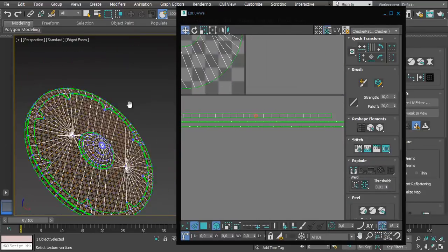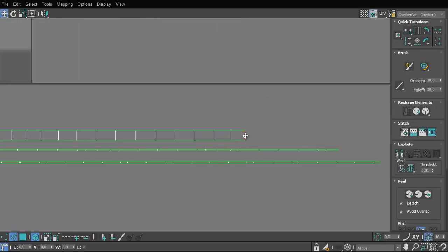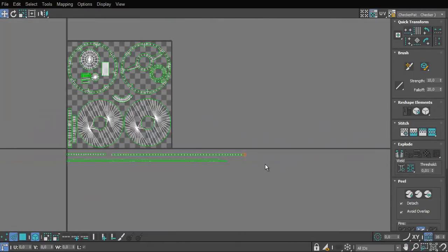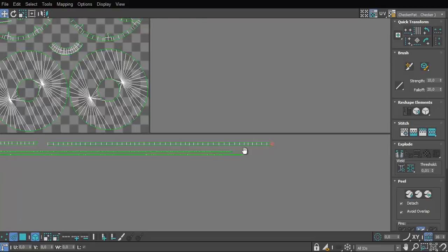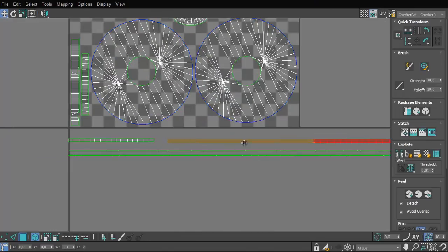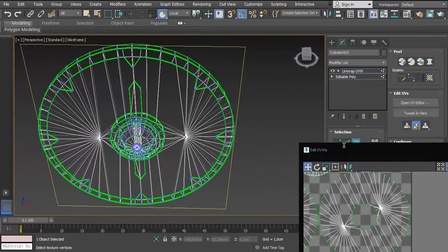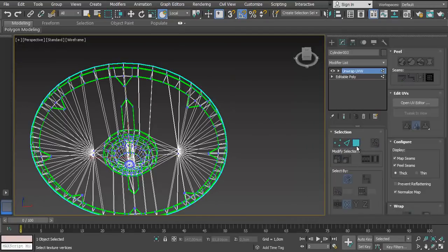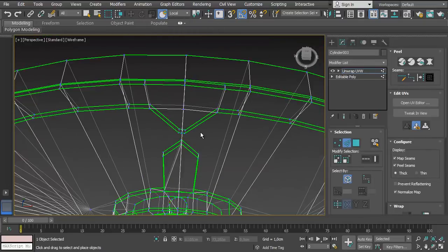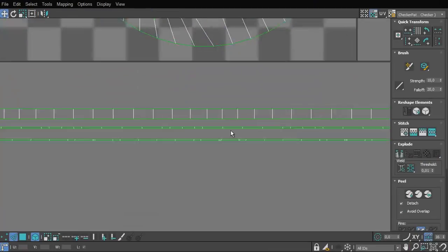And sometimes you're gonna find yourself with very big and long pieces. Sometimes you need to break them in order to actually find a right place for these pieces, and make sure you're gonna break it in a way that it's not gonna be visible, because one of the rules I talked about also is to break the UVs in hidden areas where you're not gonna be able to see it, or it's not gonna be as seen as some other areas.